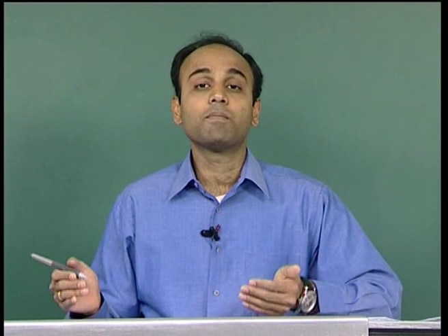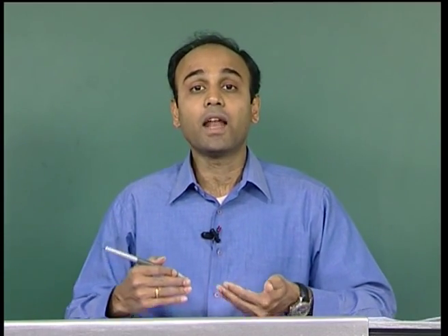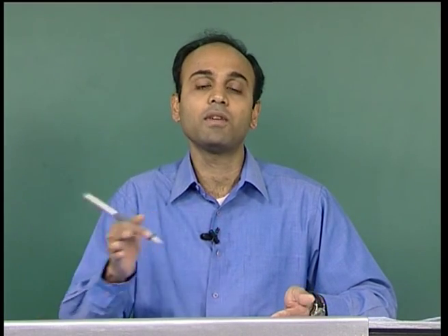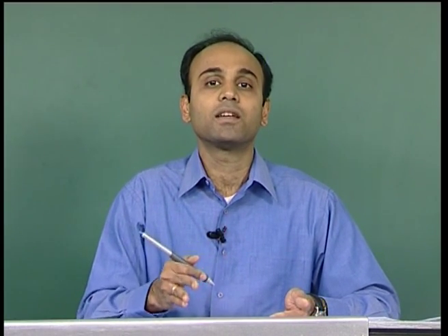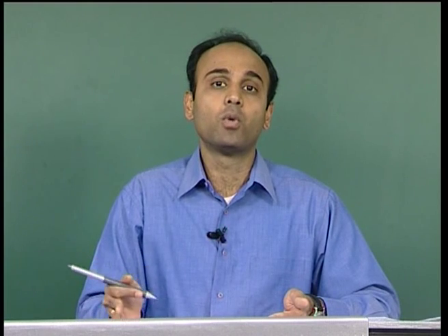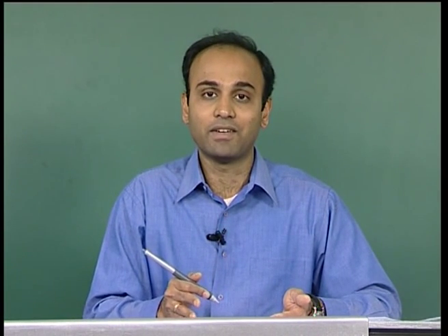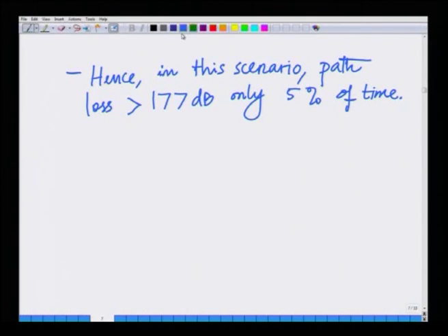Another way of saying this is, path loss is less than 177 dB 95% of the time. So, it is greater 5% of the time, which means the rest of the time it is lower, which is the same thing as saying 95% of the time it is lower than 177 dB.